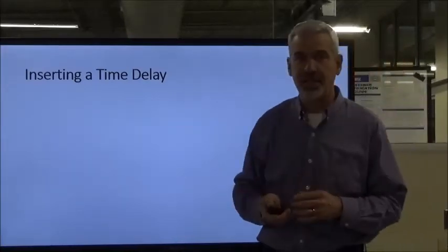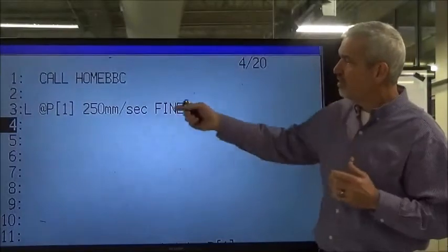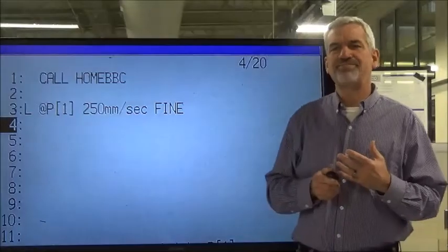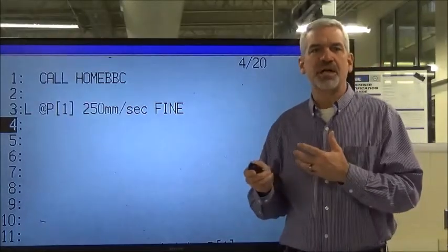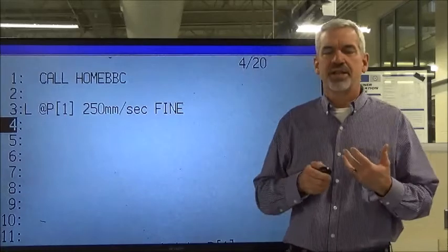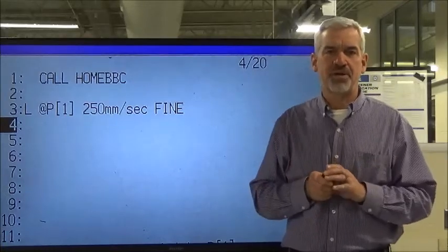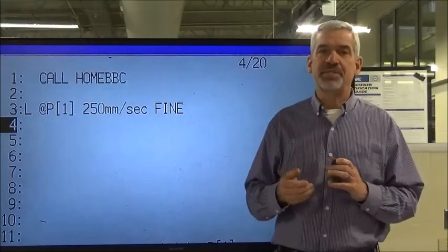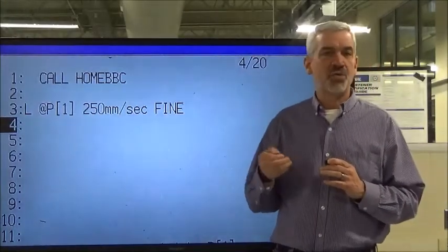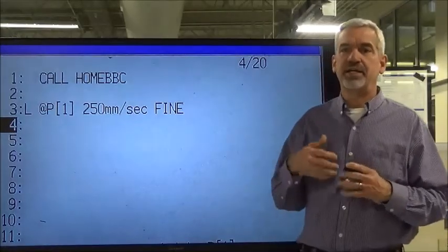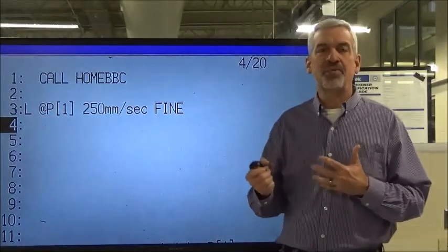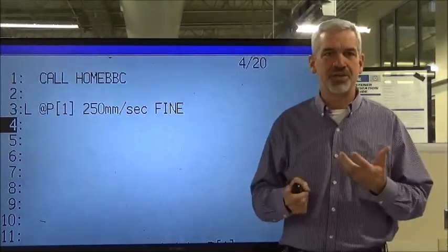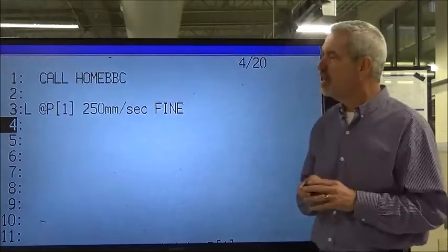We're stopped. Here's our line of programs that's doing just what I said. The next thing we want to do is common practice. Some companies do it, some folks don't. When you're running automation, and robotics is part of that automation, you want to be as fast and productive as you possibly can. But sometimes there are calls to put a slight delay in your motion, maybe a quarter second or half second. We're doing it in our project because I just want to show you how it's done. The project is not a speed race, and the time is not real critical, but I'm going to show you how it's done.